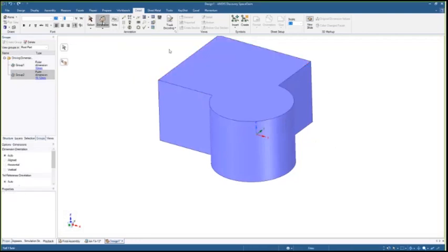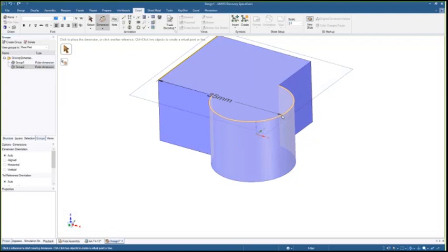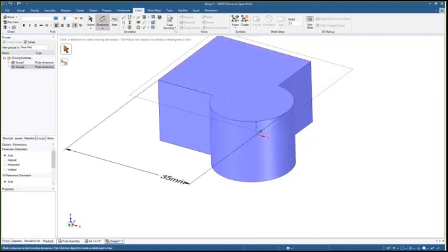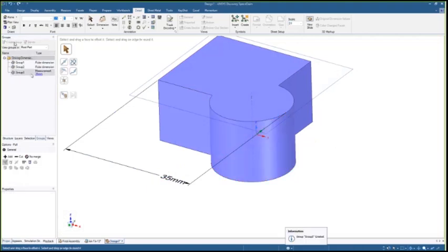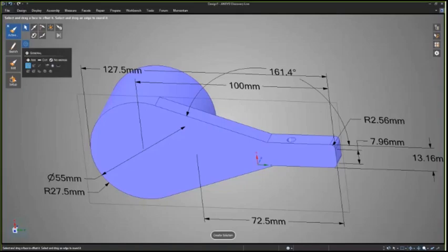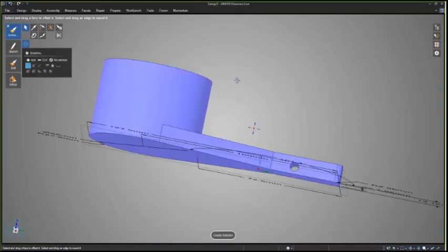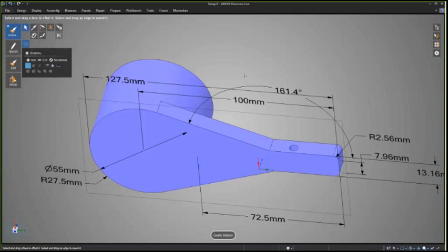The dimension tool would allow you to create the same thing here in SpaceClaim, and the setup, the interface, the interaction is very similar. So you can either use the P that shows up there. There's also a Create Groups button here, which if that P doesn't show up, you could always use. So, the point here is that you can add whatever parameter you want. You can drive the model however you see fit.